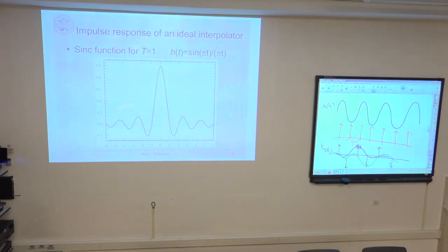And in this case, I can implement this part of the impulse response 10 samples to the left. If I need higher accuracy, I have to increase the delay. 100 samples, okay, then I have the delay of reconstruction of 100 samples, but then I have higher accuracy of representation because more of this negative part is implemented in the reconstruction. So it is a trade-off between the accuracy of reconstruction and delay. If you want higher accuracy, you must introduce higher delay into DA conversion.